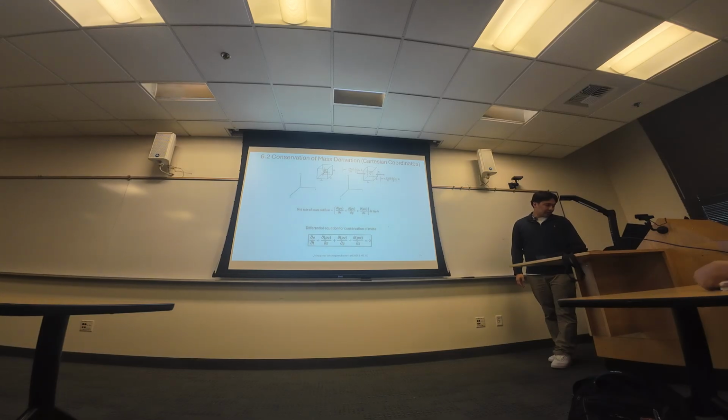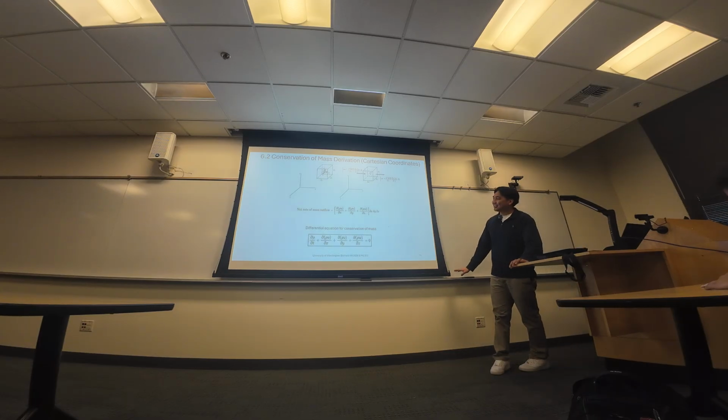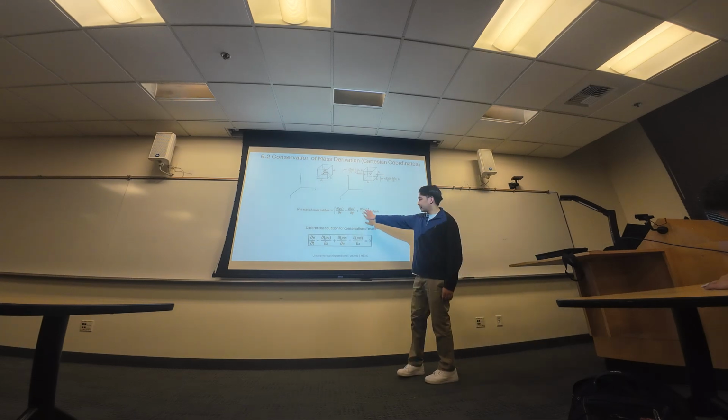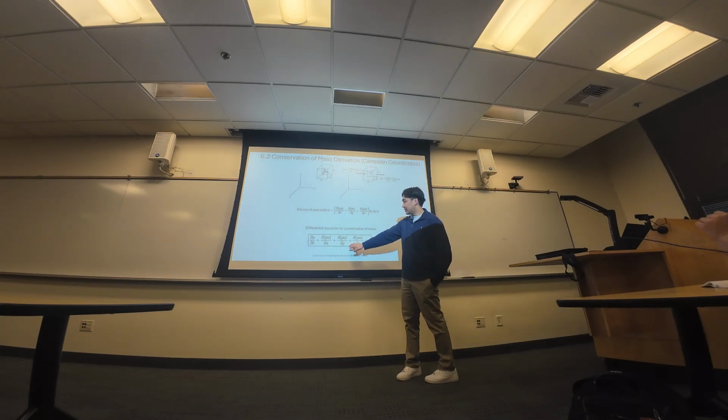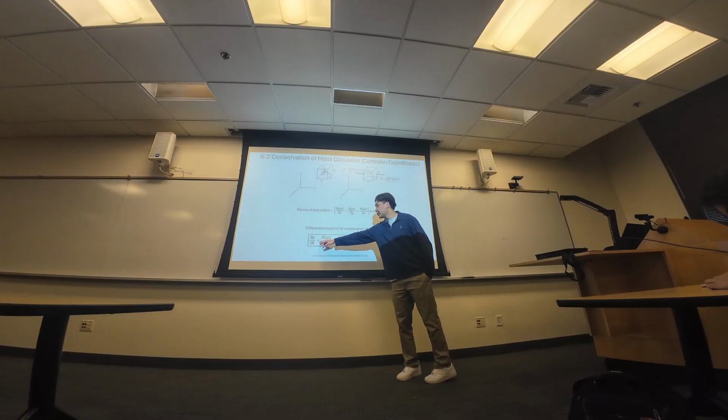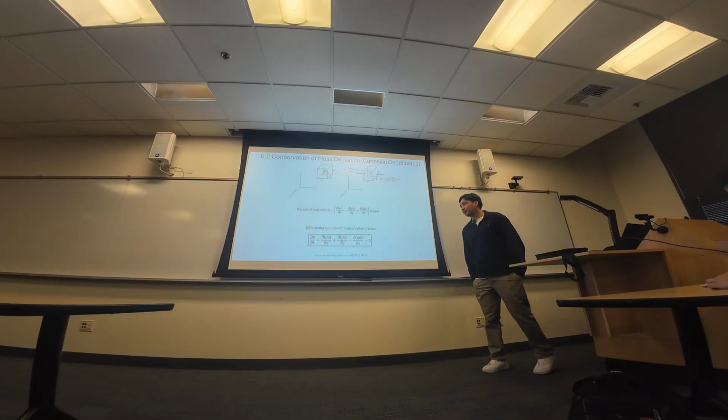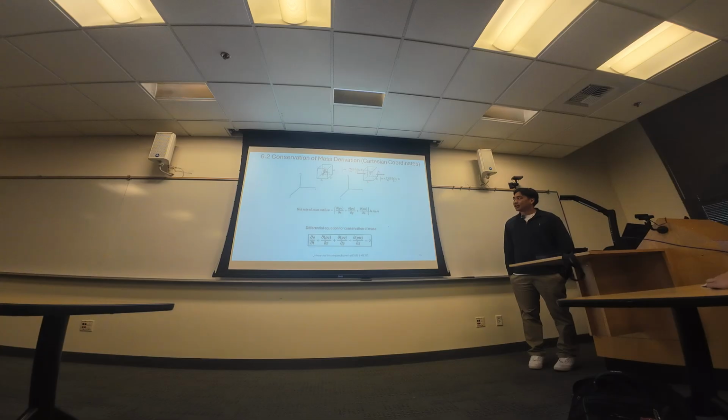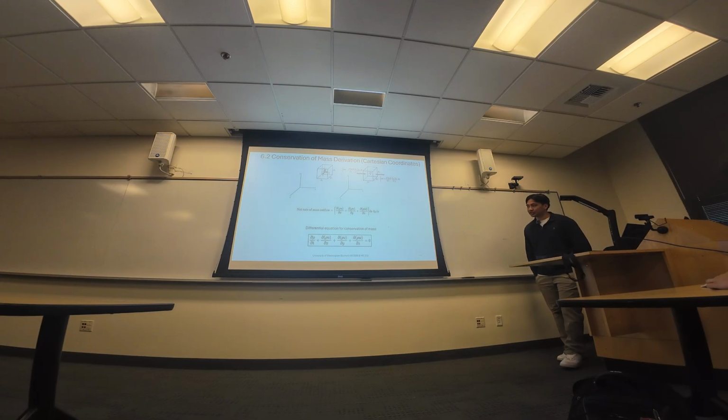So here is the main equation you want from that derivation. So this part is right here, and you added the derivative of the density with respect to time, just like your other equations that we've been using before. So that's your differential equation for conservation of mass.